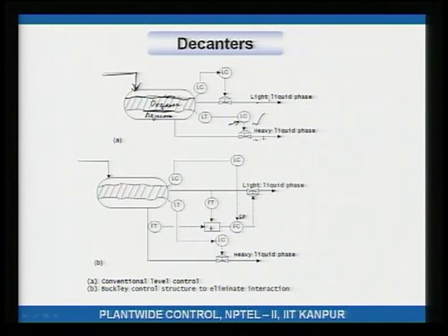the top level controller, or the total level controller. Okay, so you have the bottom level, this is the same as before, same as in A. The top level is being controlled not by adjusting the liquid phase flow, not by adjusting the top stream, but by adjusting the set point of the total flow.